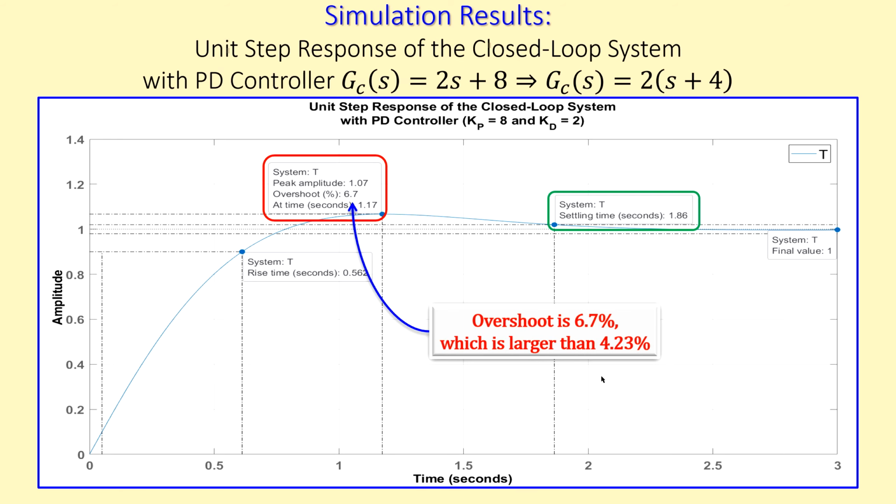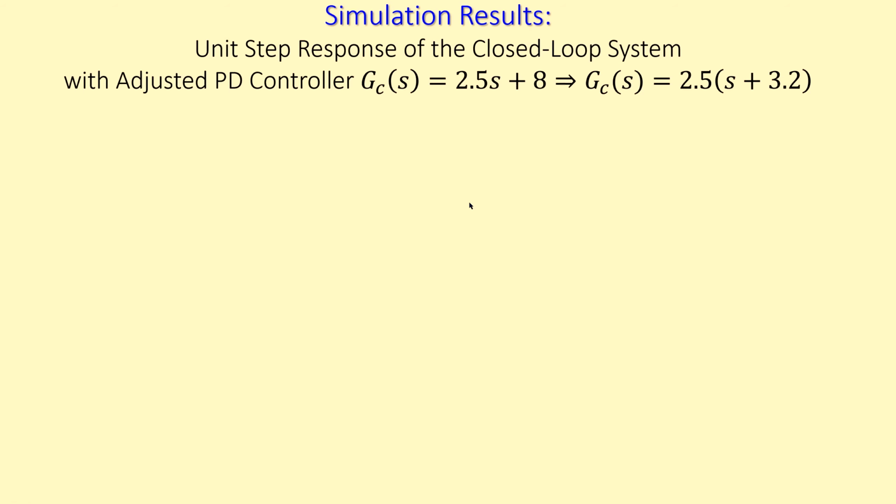So what we can do is, there are many ways to adjust this. We can of course work on the controller because the plant is fixed, so we cannot change the plant in this case. So you can change maybe the gain of the controller or maybe the location of the 0. We will see how we can tackle this. Let's look at it in the next slide.